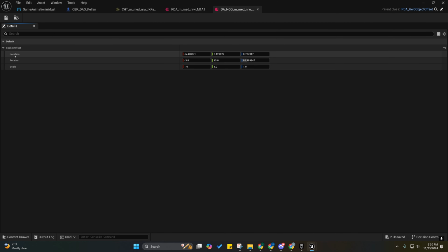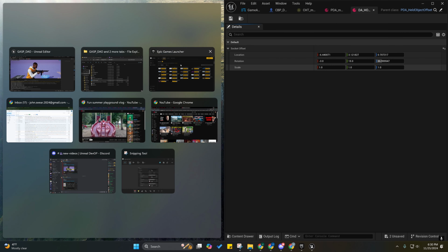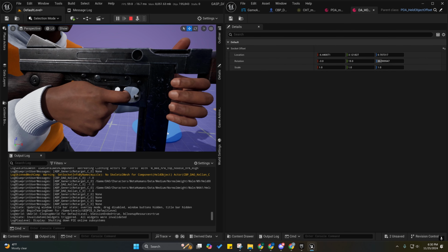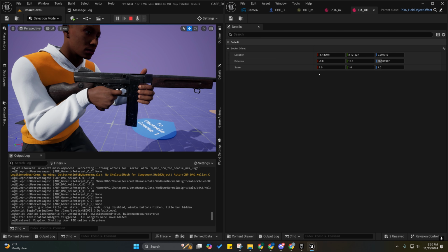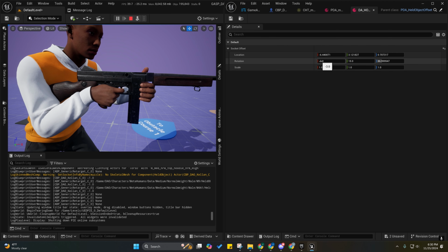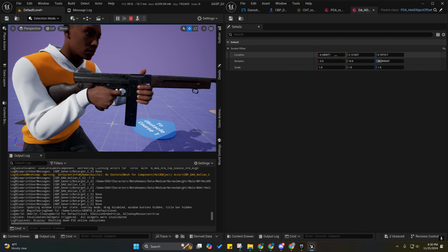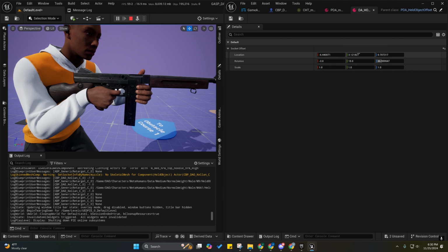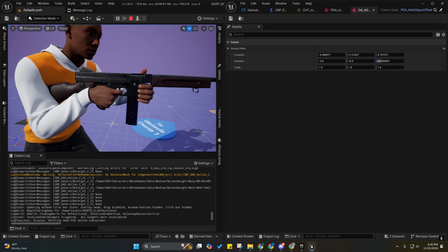So I'm just going to open up this held object definition here, and let's just say that it's messed up. Well, what I'll do then is, before I set the rotation of it, the Y and the X rotation, I'll actually try to align the position as best I can, and then I'll rotate it on the Y and the X, because the offset of the direction that this moves in will actually be the original orientation of the weapon.